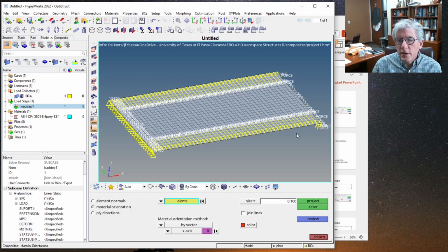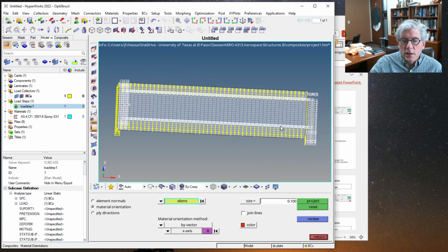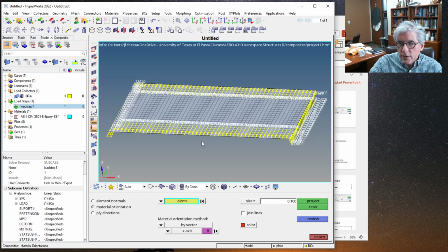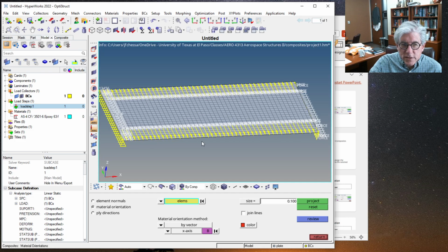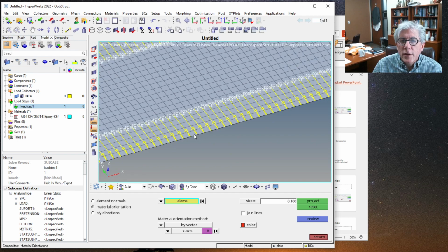Okay, so here is my finite element model. So again, these are just shell elements. I've assigned the load boundary conditions here. You can see the tip loads and then the lateral stretching loads in the transverse in the y direction, and those all go in one collector. I've done those exactly the same as I've done previously. And again, remember, for a distributed load, you can put the force on here, which is the distributed load times the area of support.